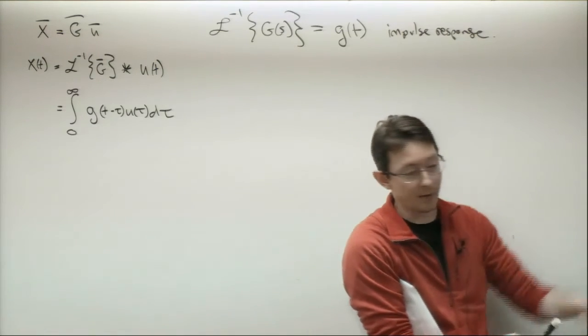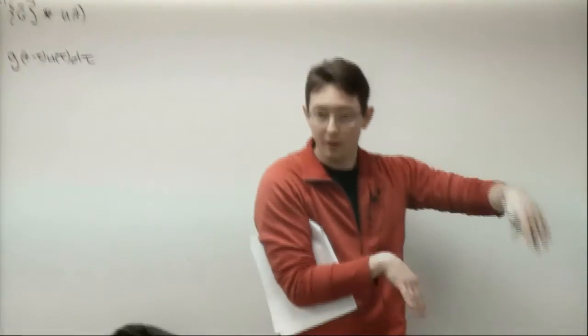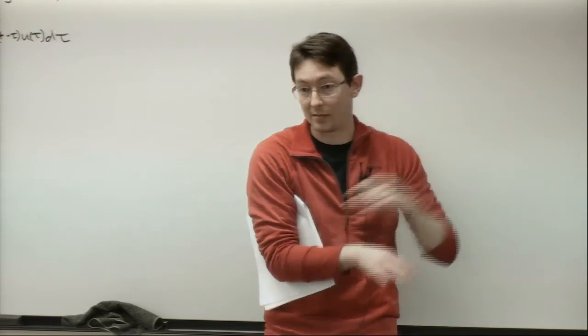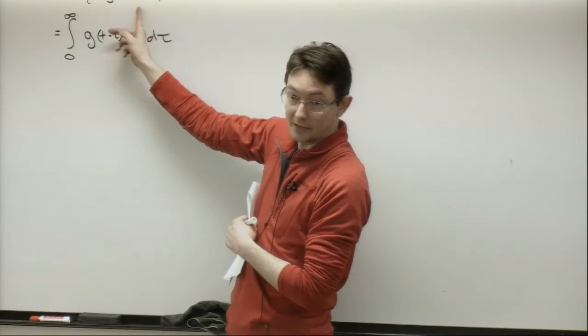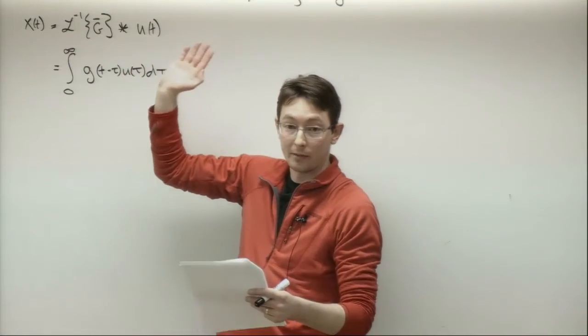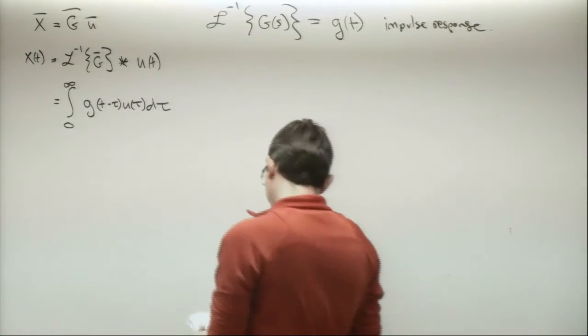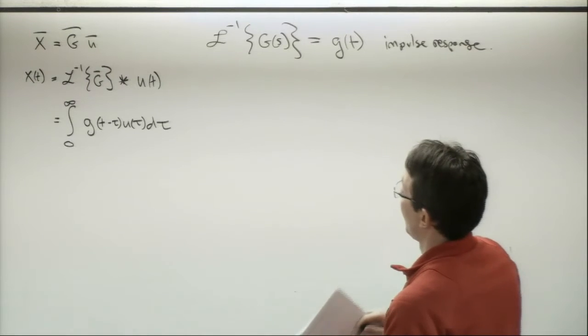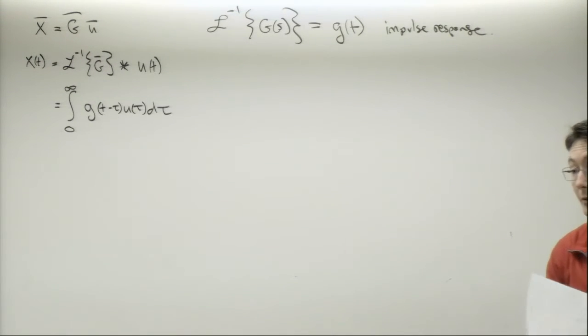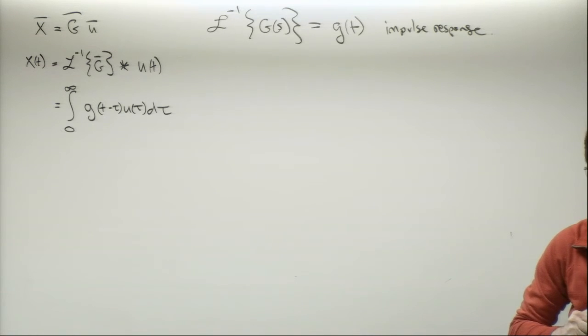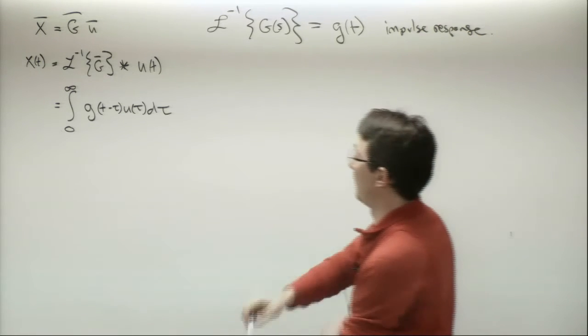And so what I might do with my wing is I might hit it with a hammer, measure its response, and then take that response and convolve it with my turbulence input u. That's not sinusoidal. It's whatever I want it to be. Okay, so now I want to tell you kind of intuitively what convolution means because I've been dancing around it, but it's really, really important.